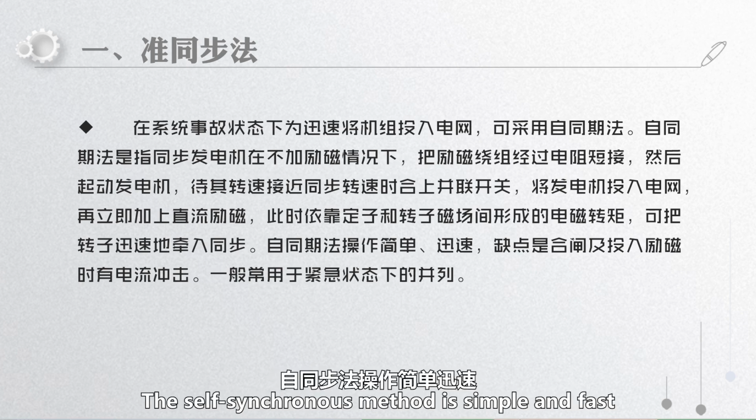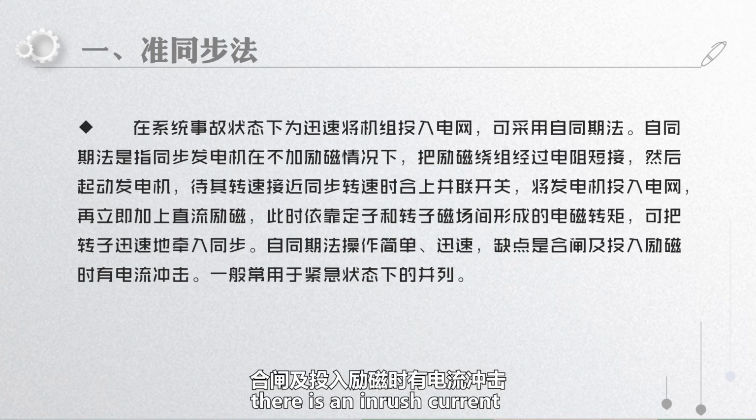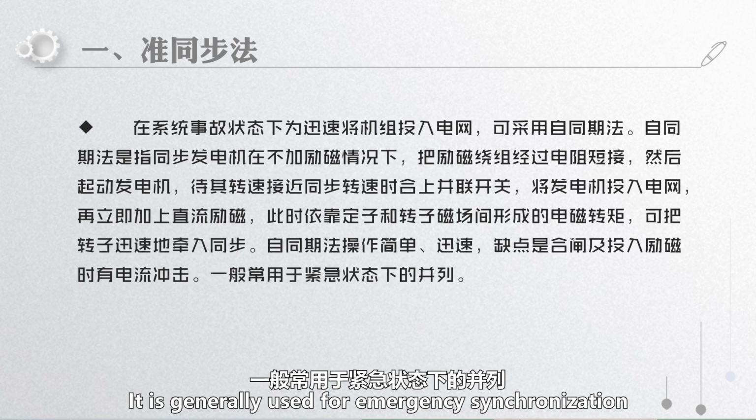The self-synchronous method is simple and fast. The disadvantage is that there is an inrush current when closing the switch and applying excitation. It's generally used for emergency synchronization.